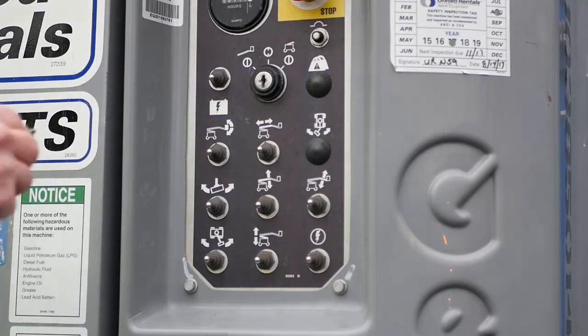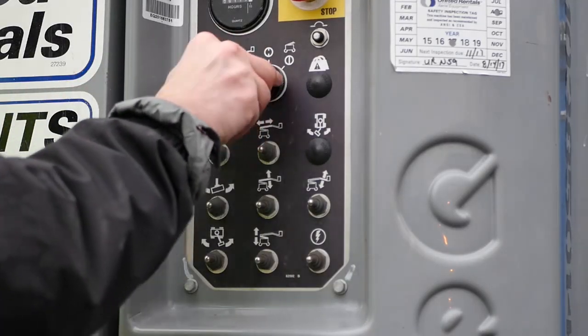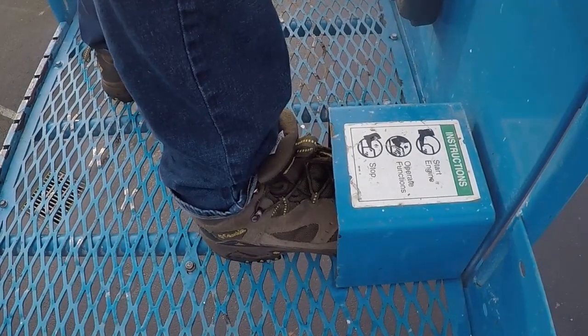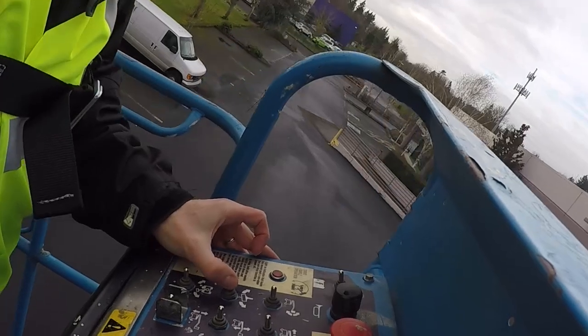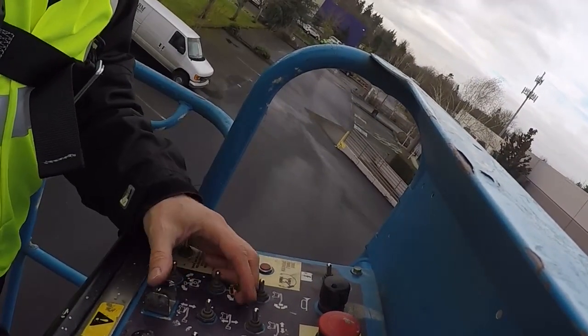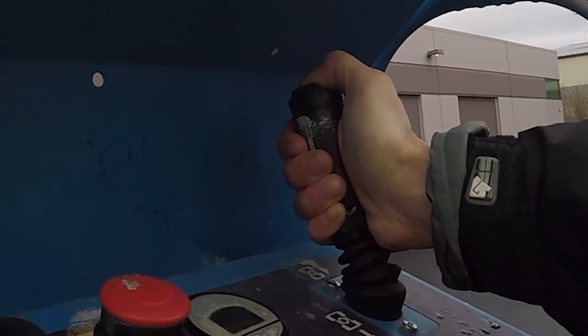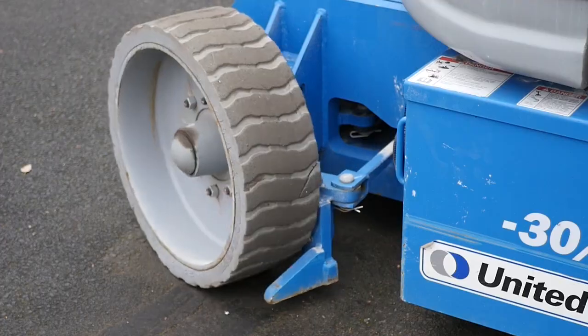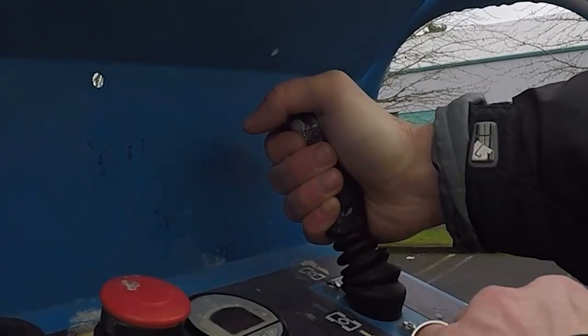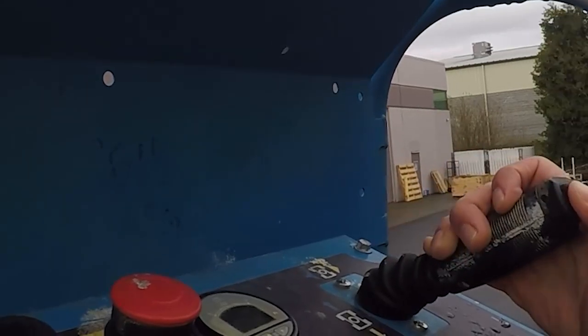To use the platform controls, rotate the control switch to platform, press the foot pedal to activate the controls, and move the appropriate switch for the desired vehicle motion. The platform will shake a little when moving. The platform also has a joystick, for driving the vehicle. The thumb controls on top are for turning the steering wheels. Press the stick forward to go forward, and pull the stick back for reverse.